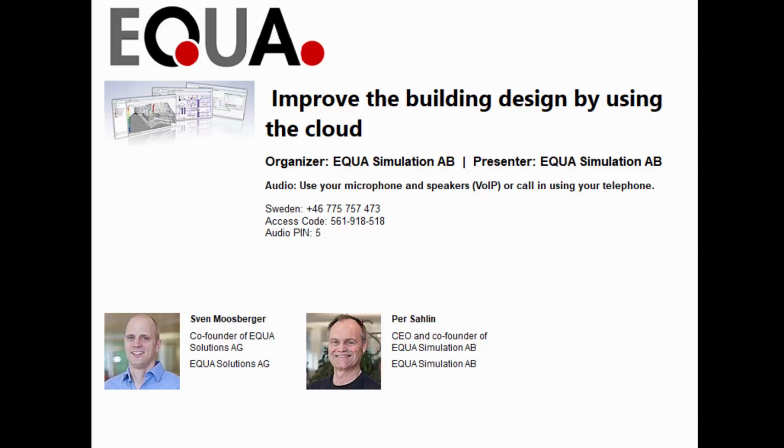It's the class of simulations where you don't just do one simulation, but you change parameters automatically and generate large numbers of simulations. We have developed a common user interface for all these parametric runs that Sven will be showing you today. The most simple type is usually called brute force, where you run all combinations of all parameters.